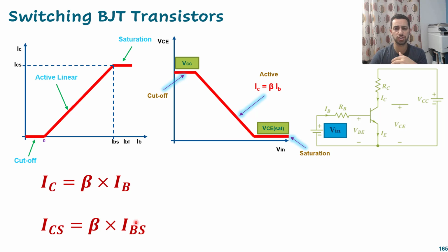And that base current, actually, will be at the edge of the active region and saturation region, to be at that corner exactly. Now, are you happy with that position here? I think we will not be very happy, because now we might go to the active region and we dissipate more heat, and we want to be more in the saturation region.